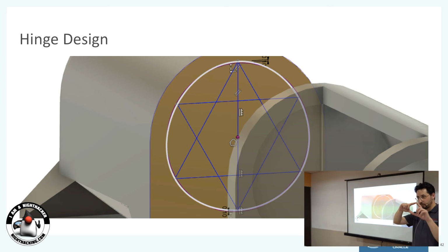And when you try to rotate a shape like this, it's only happy every 120 degrees. And in the middle, when it's 60 degrees off, it has a little bit of friction. So you can feel that in the hinge, right? So it stays open. When you start closing it, it has resistance. And then this is the stiffest position when it's exactly 60 degrees off. And then when it closes, it stays shut.